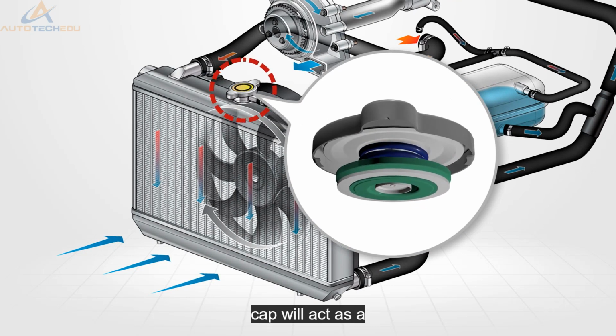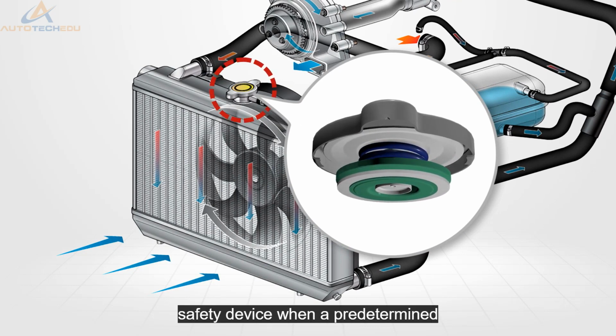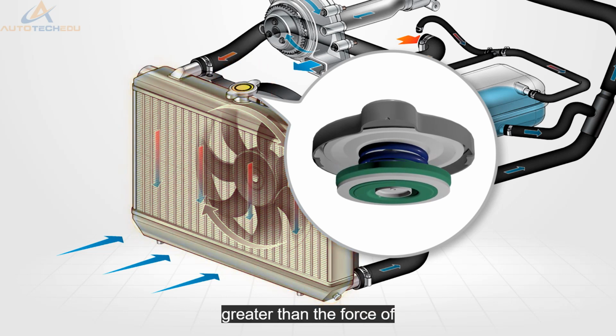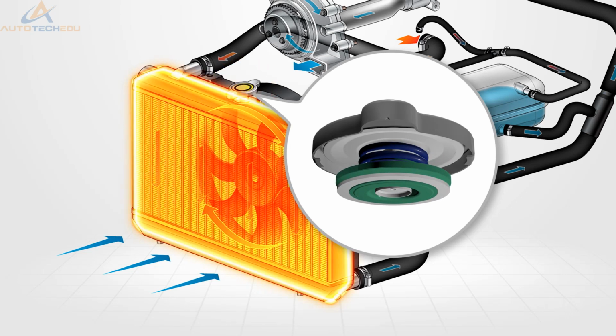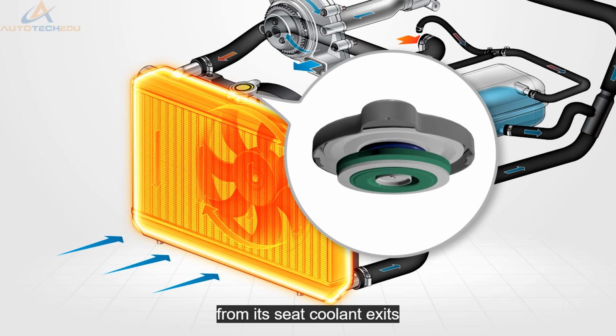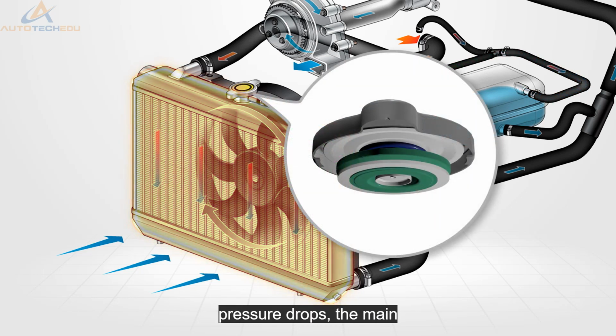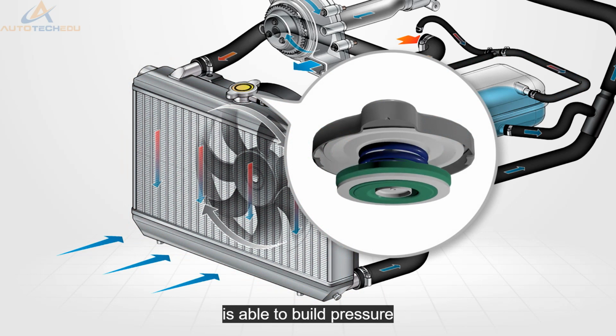The radiator cap will act as a safety device when a predetermined pressure has been reached. When the system pressure is greater than the force of the mainspring, the control seal is lifted from its seat. Coolant exits via an overflow port and is pushed to the expansion tank. As the coolant pressure drops, the mainspring pushes the relief valve closed, and the system is able to build pressure once more.